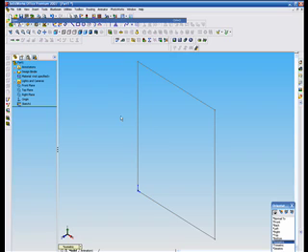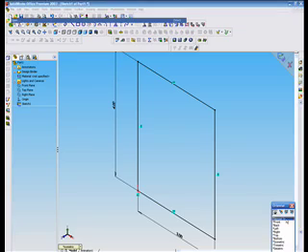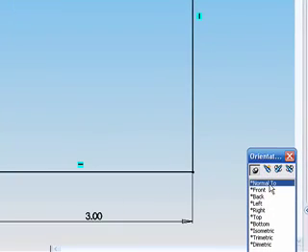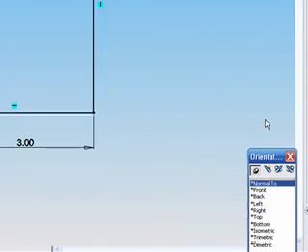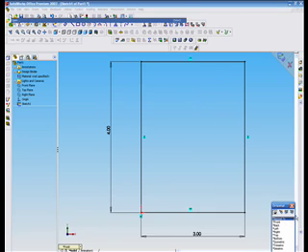So we're going to go back into the sketch, hit our third mouse button, and go Edit Sketch. We're going to go back to Normal To, so we get that chalkboard kind of thing in our face happening. Hang on, I just screwed up my view. Alright, so here I can add some 3D parameters to it, like giving it an extrusion.